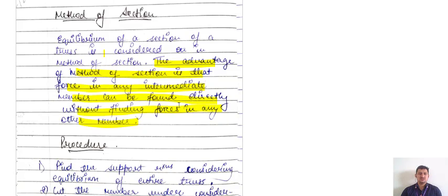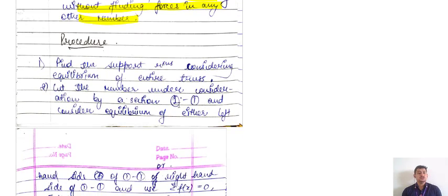So what is the procedure behind it? The procedure says that first of all you have to find the support reactions considering the equilibrium of the entire truss.